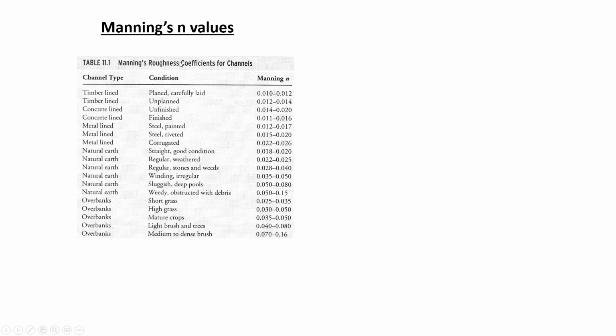So these are the N values. You won't have to face that uncertainty in this class. I'll always just tell you the N value or give you a table to look it up, but I'm just letting you know that if you're going to do this kind of engineering in the real world, selecting the correct N value is sometimes the hardest part, is feeling really confident that you've got the right N value.